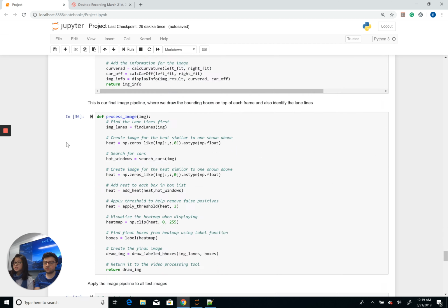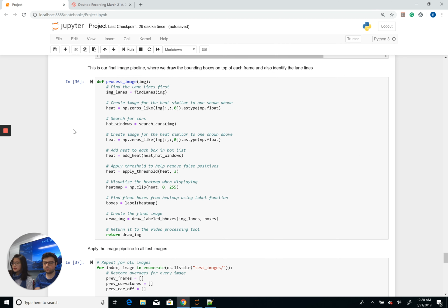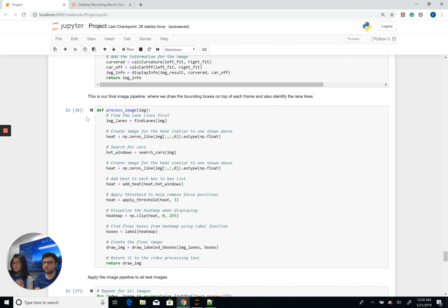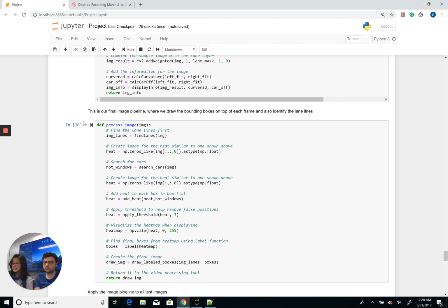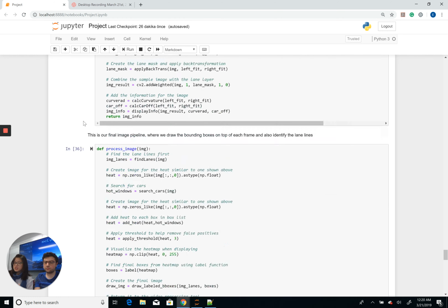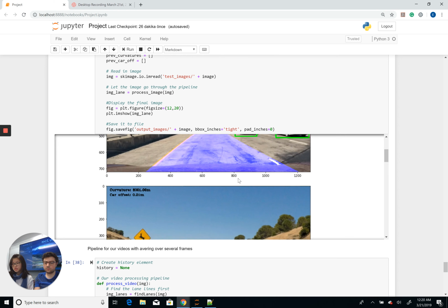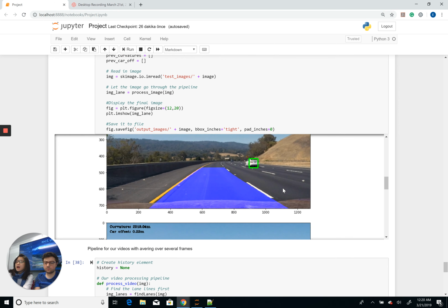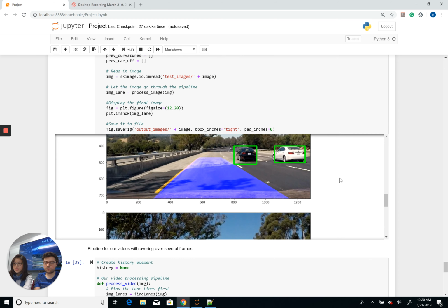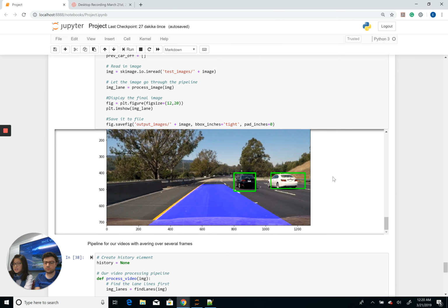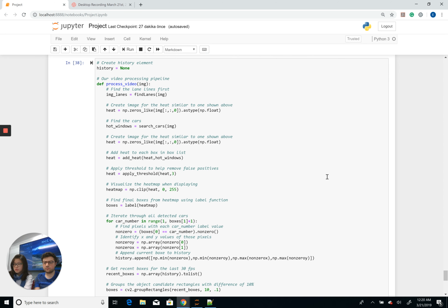The lane detection part also started with applying a region of interest to the image, which prevents redundant calculation of areas without lanes or anything we might be interested in. The next step, we apply a perspective transformation to better detect the lanes. We then used an HSV color mask to detect white and yellow lanes and combined them with a Sobel filter to better detect the edges. After completing the image processing part of our project, finally we wanted to process our project video to see how well our model performs with real-time detection at 30 frames per second.